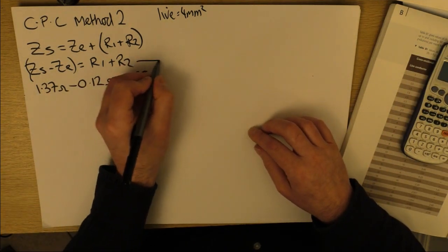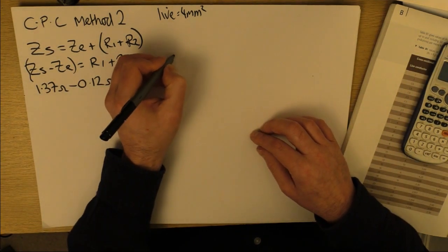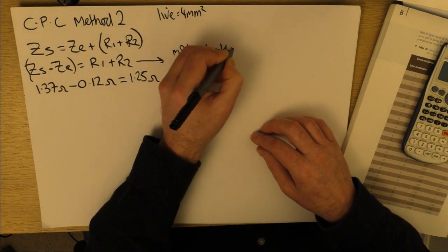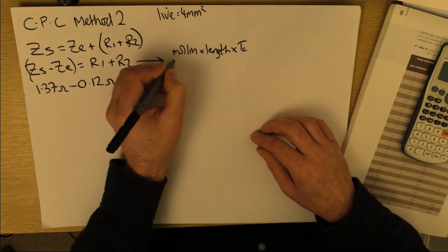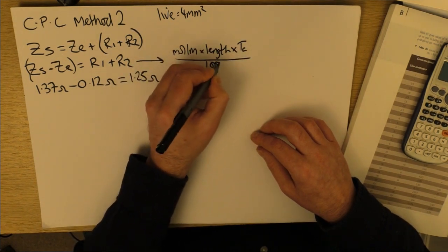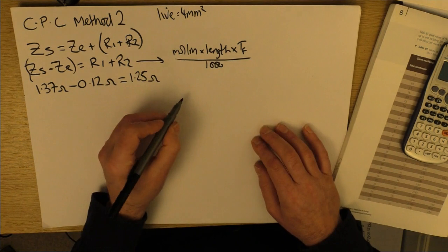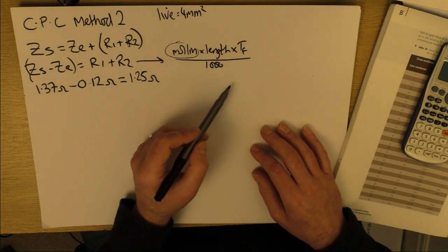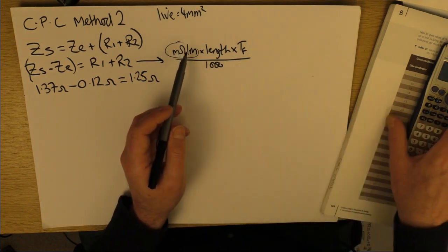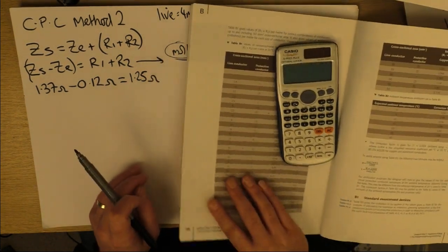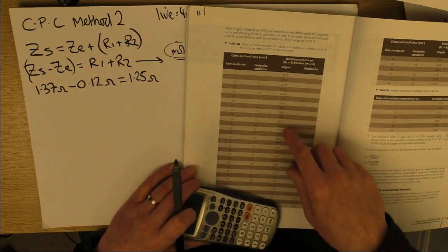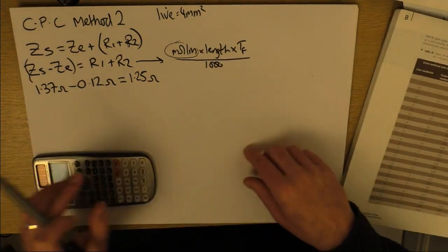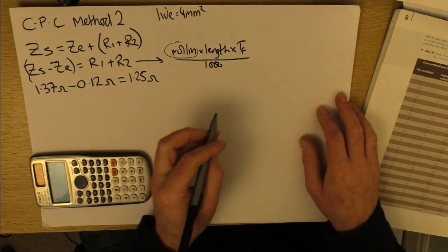So we need to kind of expand that a little bit. The equation for that times that temperature factor divided by 1000. So what we do, we transpose for that, and then in the same way we did with the volt drop, we can use this table here to find a maximum milliohm per meter value. So transposing that, you'd multiply out the 1000.